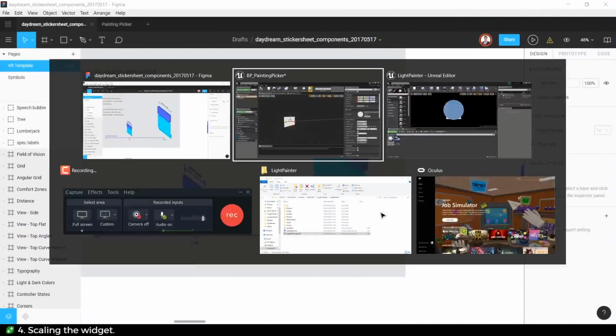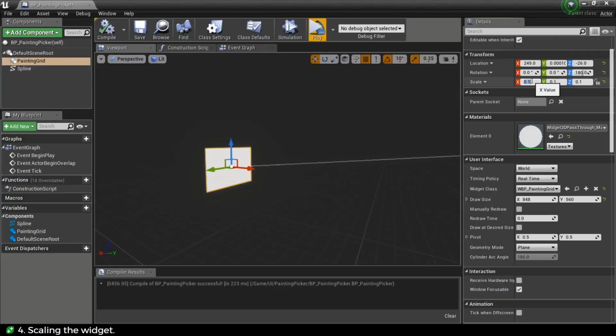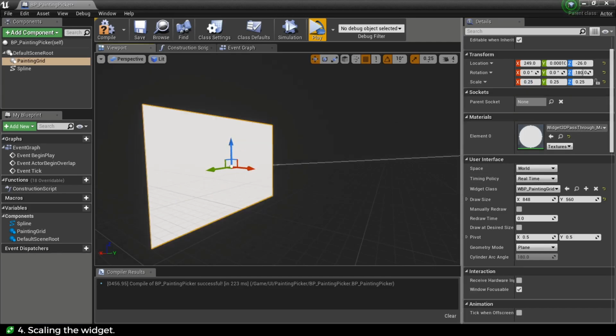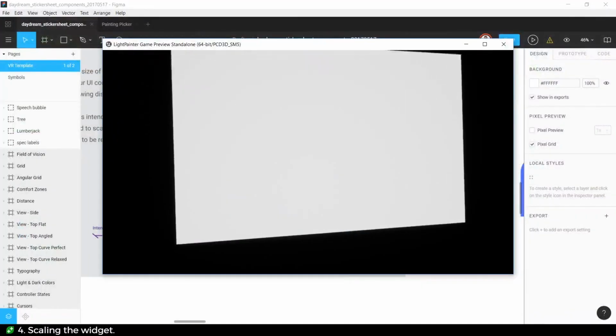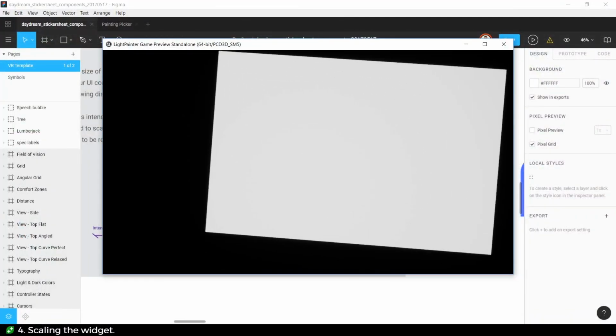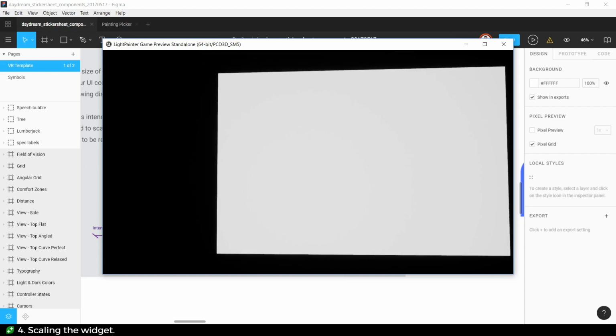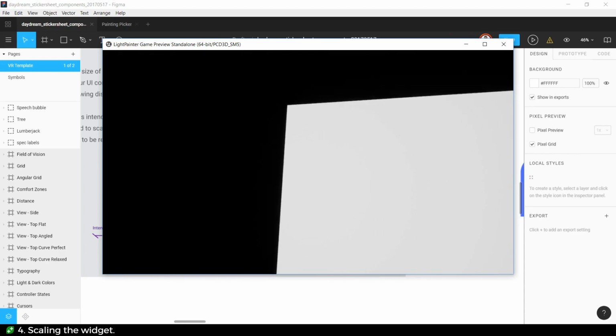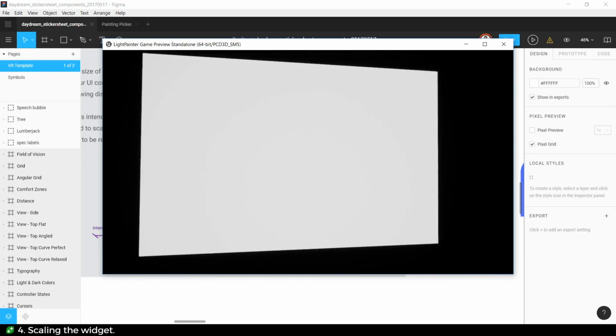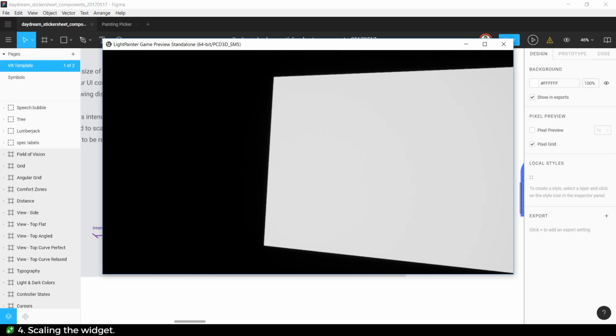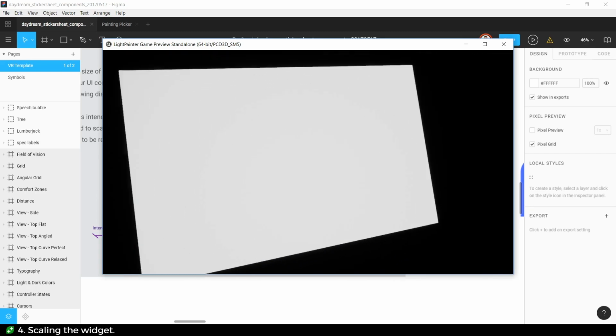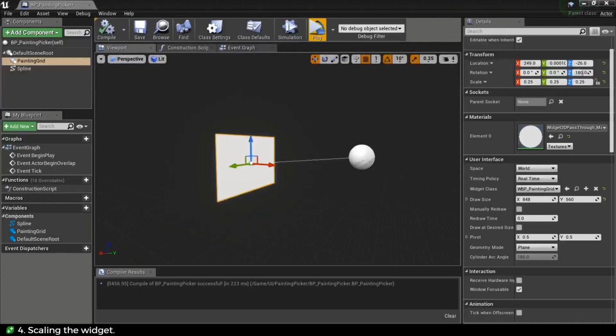So the way we can do this is go to the scale again and basically just multiply with the asterisk by 2.5. So multiplying by 2.5 and copying that into the other scales, you are going to get something more correct. Go ahead and hit play. There we go. We've got something that is basically the right size. That is how you set up your scale and your depth for VR from the dim measurements that we had.